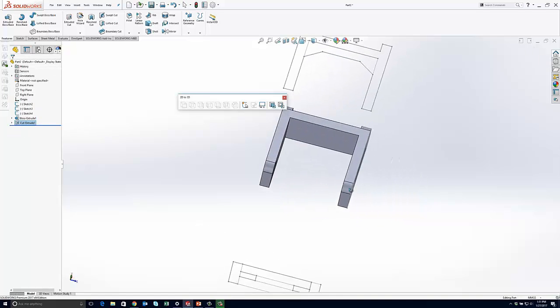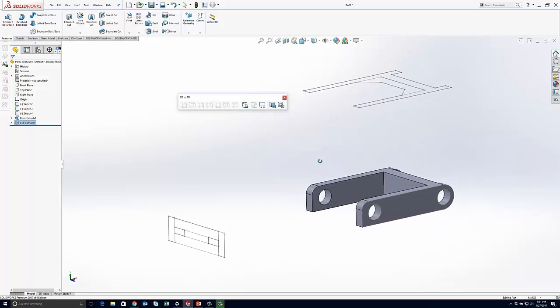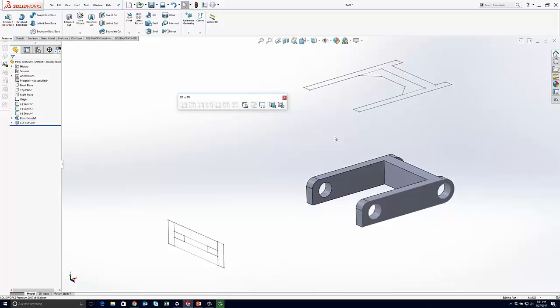So we can see we're starting to shape up here and have a part that is looking like our 2D views had shown us here. Now the last thing that we want to create here with this part is our rib. So once again, I'm going to use my select chain to grab a couple different sets of geometry here. And I'm also going to control select. So I just hold down control, do the same thing when I'm picking my multiple chains.